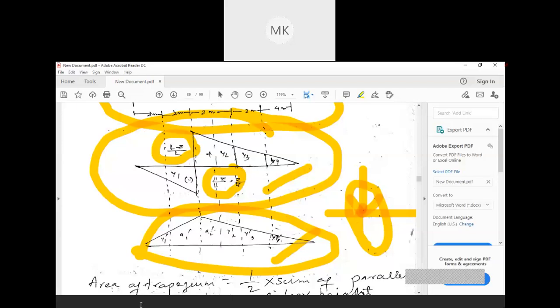for finding out shear force. You need to remember two formulas. One is for the above part, L minus Z by L, and for the below part it is simply minus Z by L. Okay, and for the bending moment also you have to remember only one formula, L minus Z by L into Z. Okay, so that you can find out FC and MC.